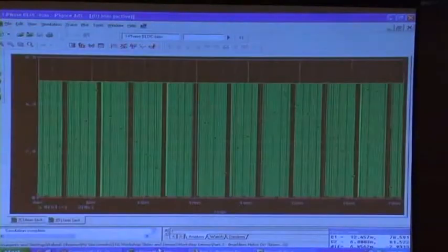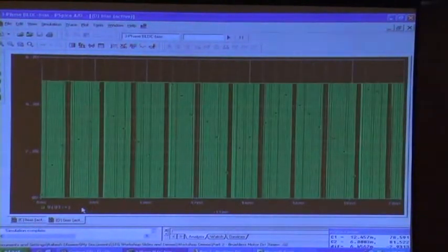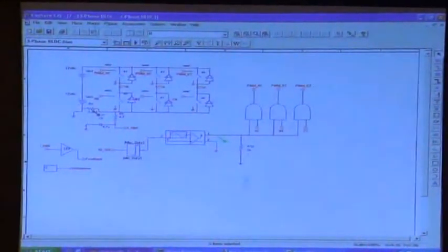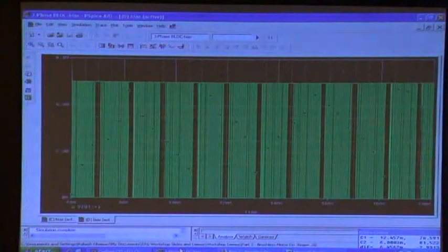So that's what I think it's going to show. So this is the voltage at the output of the PWM. The PWM pulses essentially look like this. The voltage signal is from 0 to 5 volts. That's what we have set.